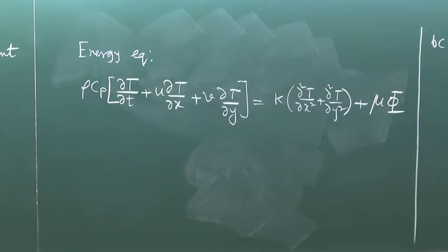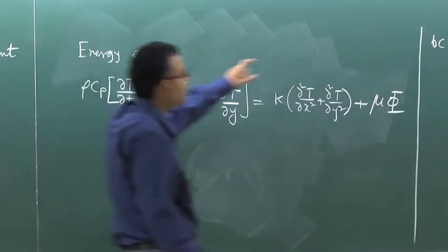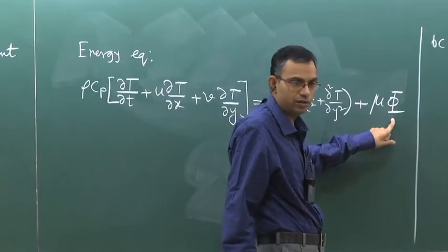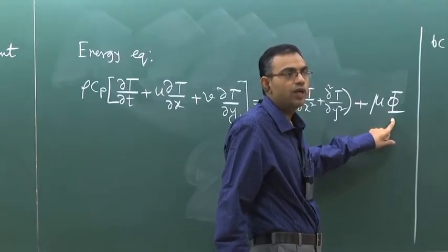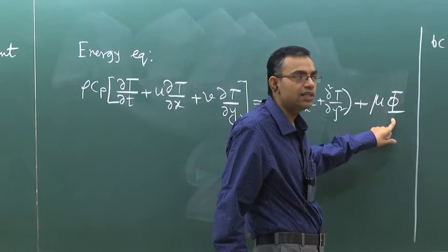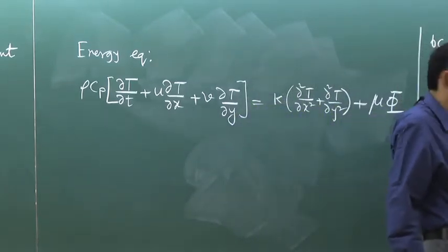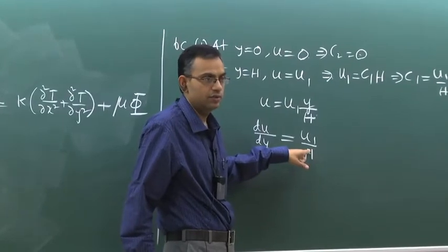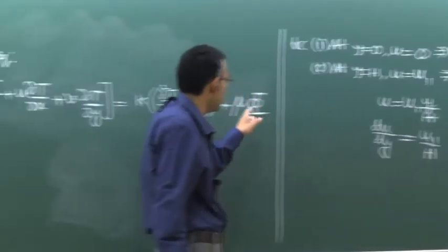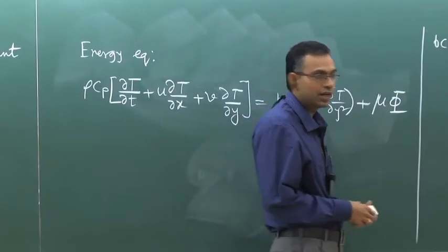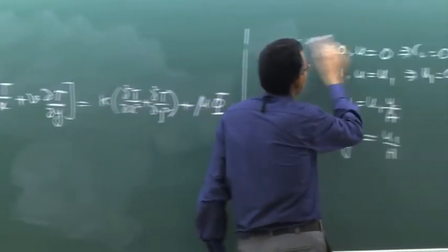We have considered the viscous dissipation term, but we will analyze later on whether this term is at all important or not. We have kept it in the analysis because it at least has the potential of being important, because h being small, the square of this may be large. So that gives the motivation for keeping this term.